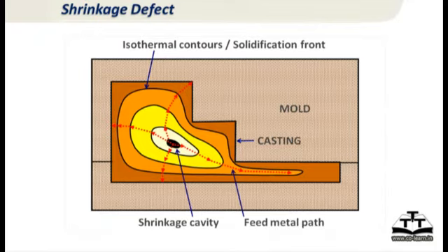And what happens to the white region? When the white region is solidifying, everything else around is already solidified, and the white region has either directly or indirectly fed the rest of the casting. That ends up with a hole when that is freezing, right? White has fed yellow, and yellow has fed the orange region, orange has fed the brown region. So the white region has directly or indirectly compensated for the volumetric contraction of the rest of the